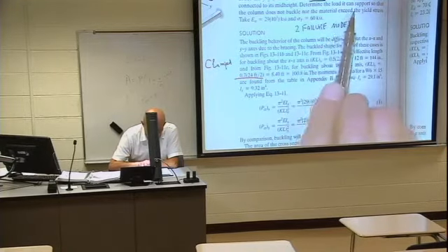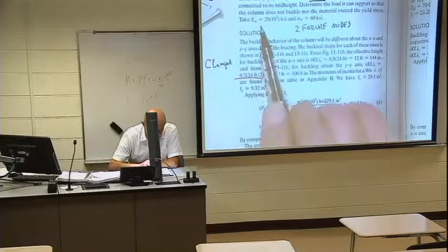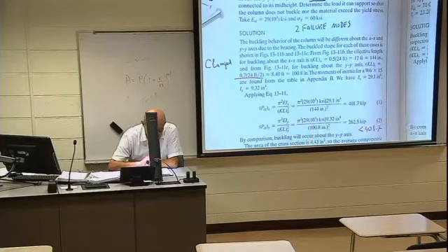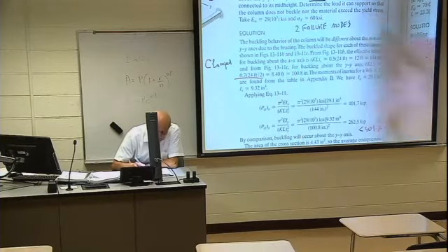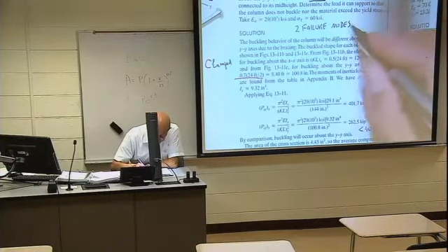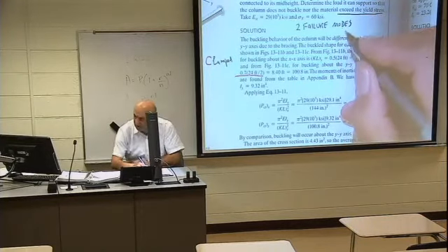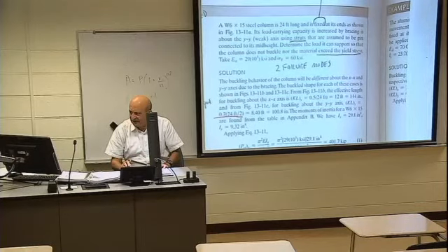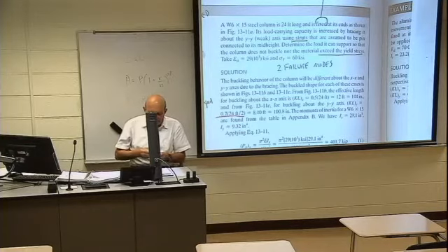Determine the load this system, this column, can support so that the column does not buckle, nor the material exceeds the yield stress. So look please, it does not buckle, and nor the material exceeds yield stress, that is the strength requirement. So there are two failure modes. So I will show you this problem again.